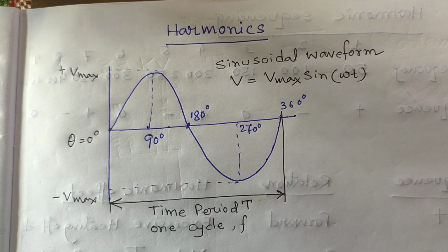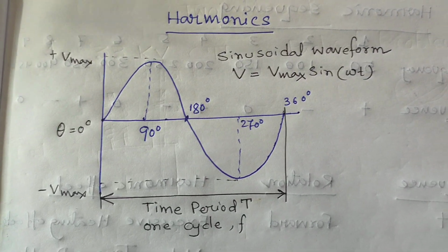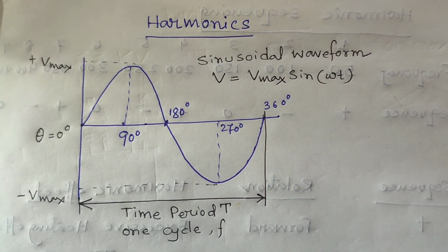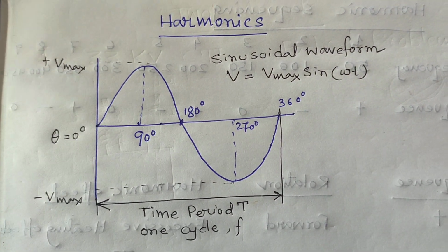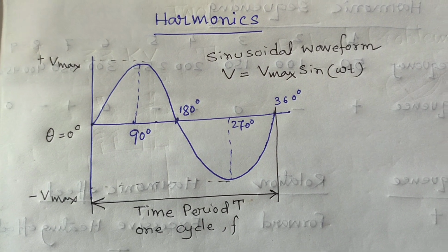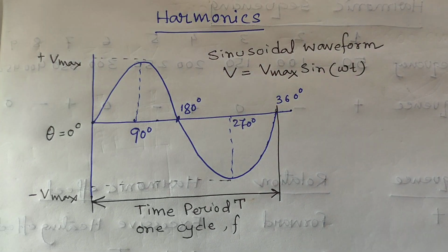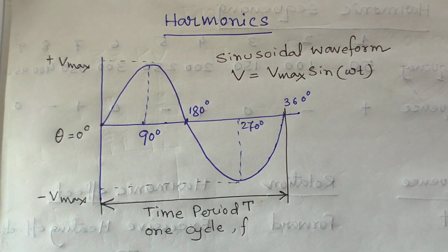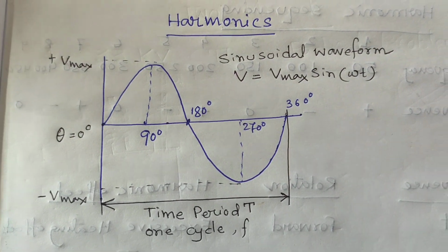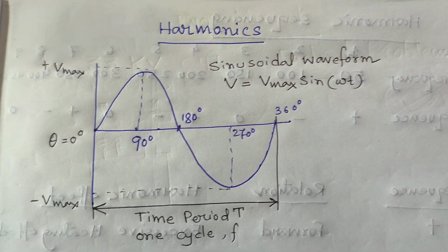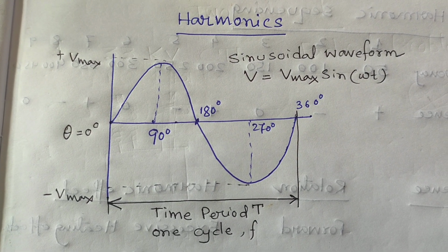In an AC circuit, a resistance behaves in exactly the same way as it does in a DC circuit. That is, the current flowing through the resistance is proportional to the voltage across it. This is because the resistor is a linear device, and the voltage applied to it is a sinusoidal wave. The current flowing through it is also a sine wave, so the phase difference between the two sinusoidal waves is 0.